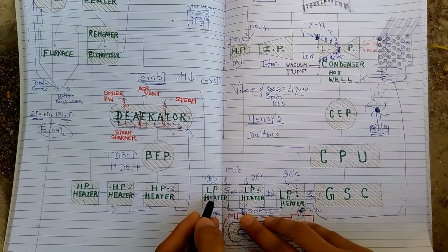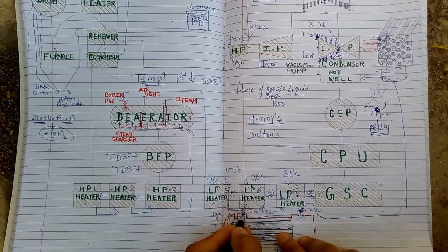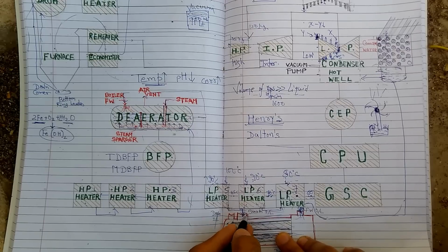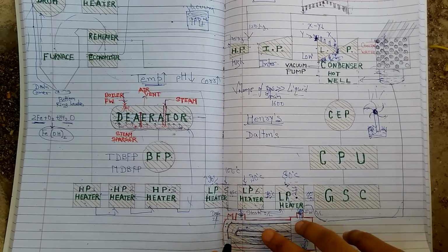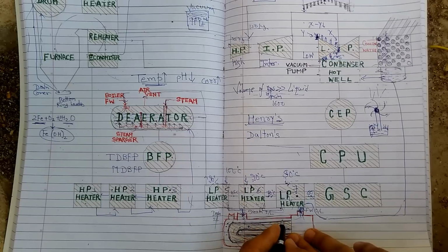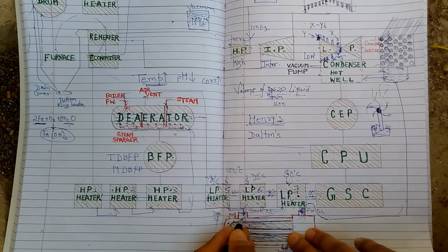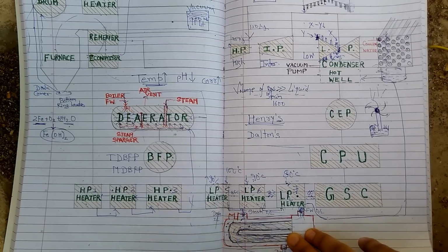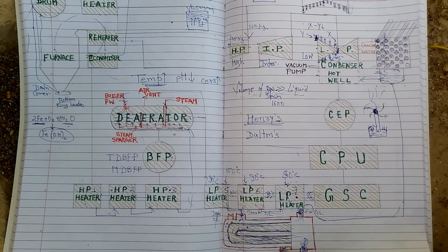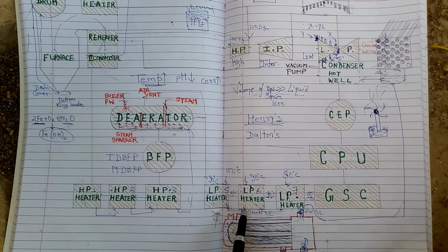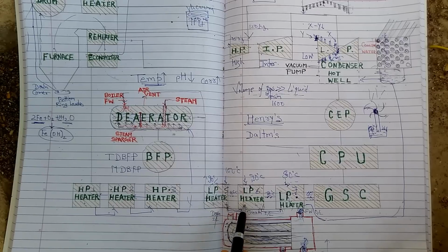What we know is the steam pressure here is maximum in LP heater 5, lesser in LP heater 6, and lowest in LP heater 7, and the condenser has vacuum. So out of this U tube also, the pressure will be highest in LP heater 5, lesser in LP heater 6, and lowest in LP heater 7. So the drain of LP heater 5 can naturally be sent to LP heater 6. Okay, I'll put a drain line from 5 to 6, and that will send the drain to 6 naturally, because the pressure is higher here and lesser here.